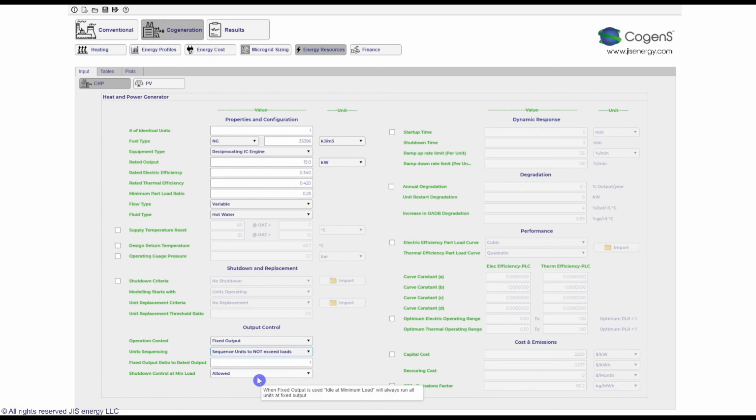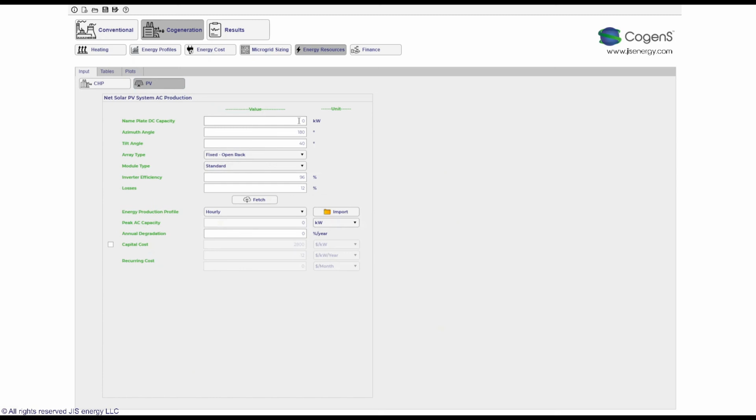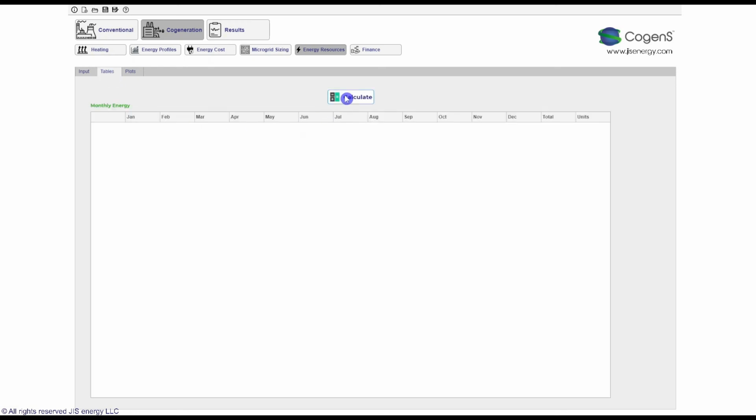Great. Now let's use a 125 kilowatt nameplate for solar. We'll keep everything as is and call for the NREL API. Good. Very close AC output to what I'm looking for. We'll change the price point for the solar to a lower bracket. 1,800 per kilowatt seems fair. Now I'm ready to calculate my model.